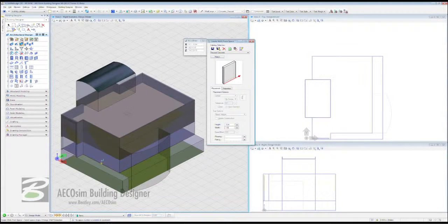And now that means that we can come down to this other space here. And finally, our ground floor, we're going to change the material because we're going to zoom in here and choose brick. And again, let's use our history just very quickly. 16 foot, just in case anything changes. 1 foot for the thickness. Come in here, highlight the space, click inside, and once more to set. And our walls have been set.